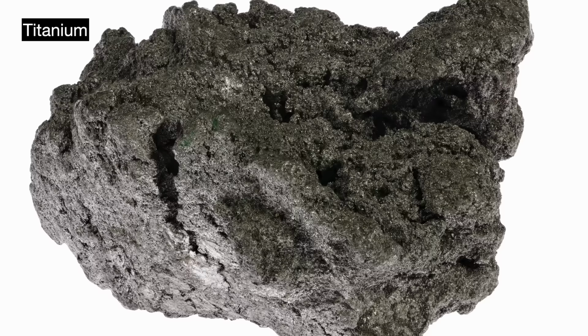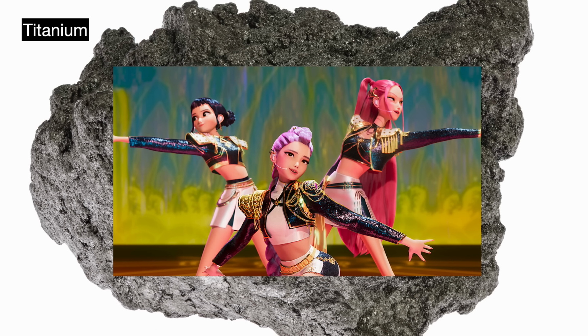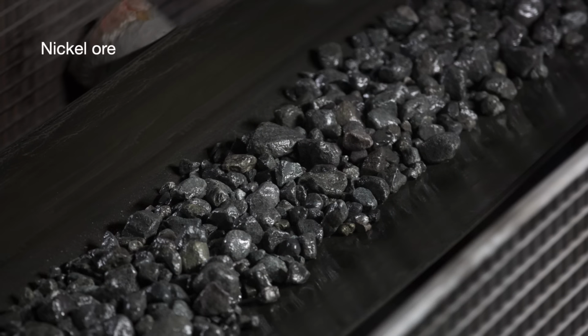The titanium silicides have a two-step formation method, which is quite famous. Famous in the semiconductor world. Nothing like K-pop demon hunters. By the time of the 45 nanometer node, the fabs are already moving on to cobalt and nickel, but titanium is still good for illustrating what is going on overall.